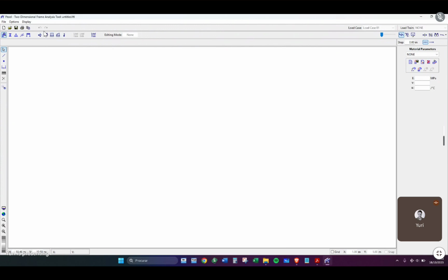In this part here, whenever we click through these tabs, you will see that this right corner here will change. Okay, so we'll talk about this in a minute. Here we also have load conditions. Here if you have nodal loads, here the application of nodal moments, and here when you have uniform loadings and when you have non-uniform loadings, so triangular forces, for example.